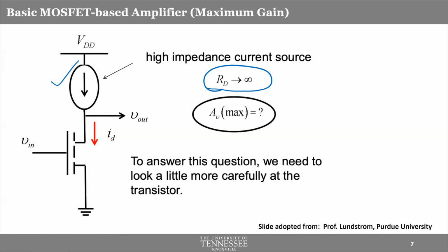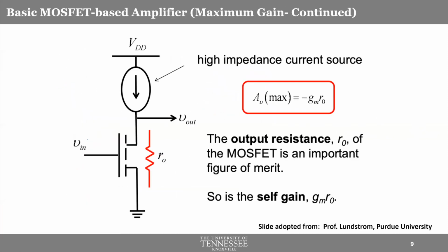The reason is we are ignoring another part here. We are considering the transistor to be an ideal switch, so whenever it turns on, it will just allow current flow relentlessly. But that's not really the scenario. This transistor will have a resistance of its own between the drain and source through the channel, right? And let's see how that resistance plays out here. Let's go to the next slide.